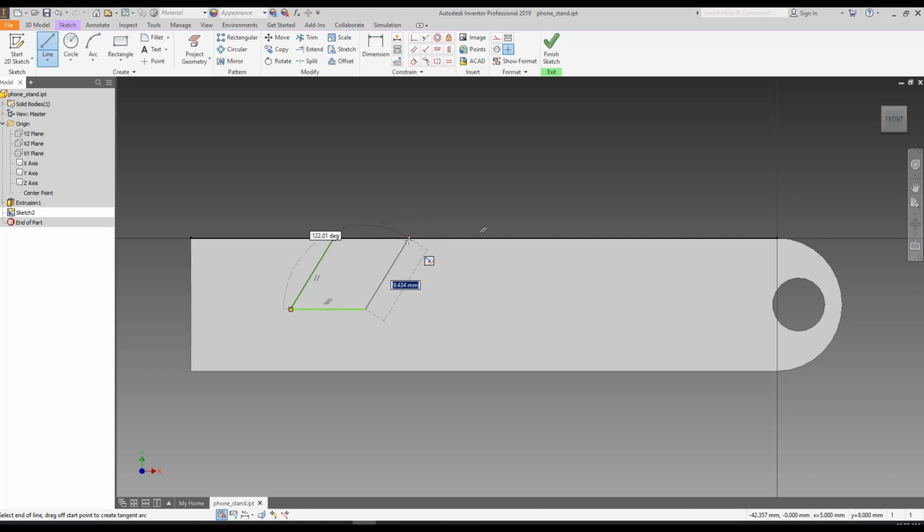That means that the 2 angled lines are parallel. It's kind of hard to show you here, because if I move the mouse marker, the constraint symbol would disappear. So if I'm out here, there is no constraint showing that these 2 lines are parallel. And here they are parallel, there they're not parallel. I'm going to set them so they're not parallel, just to show you how to use the parallel constraint tool. So I'm just going to click so I snap onto the upper edge. So just click there. And then I would want to do one more line from here to here.